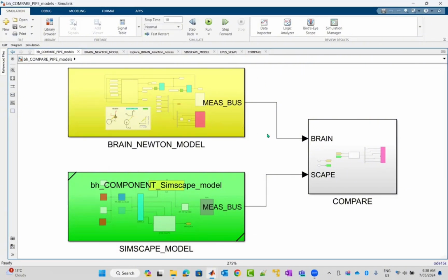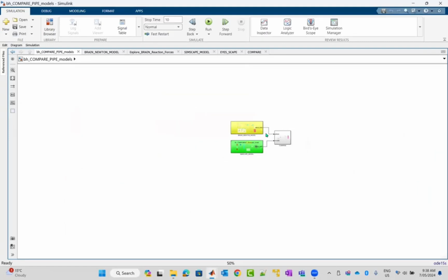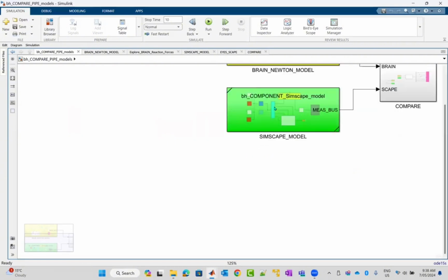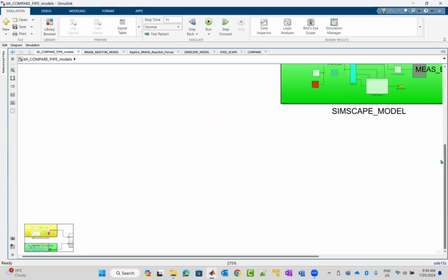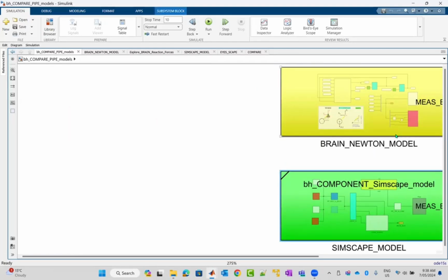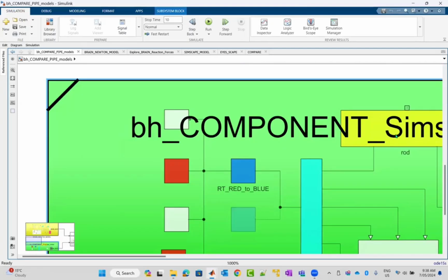Here are three keyboard shortcuts for navigating a Simulink file. If you notice that the blocks in the Simulink file are really small, you can zoom into that system by holding down your Control key and then hitting the plus key. Each time you do that, it will zoom in. Similarly, if you find that you've opened a Simulink model and you've got your face pressed to the glass, so to speak, the shortcut keys for zooming out are Control and minus.